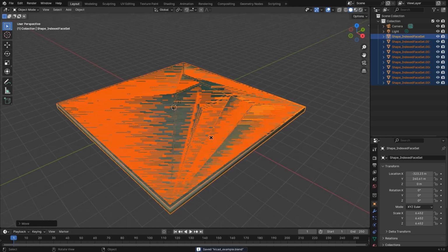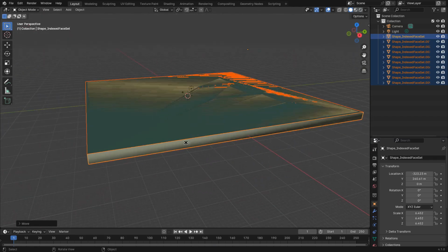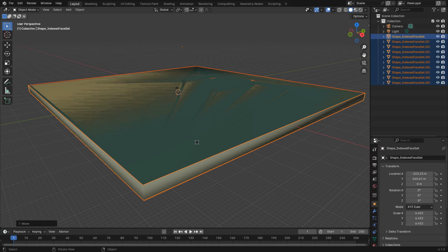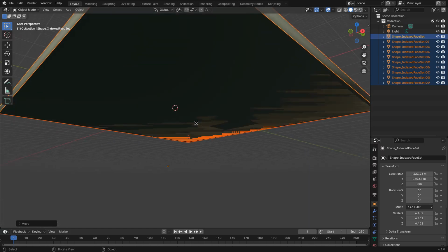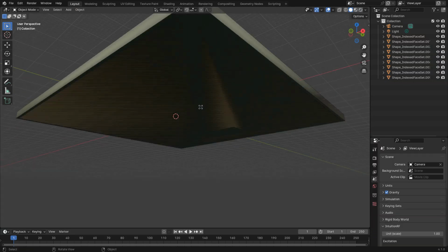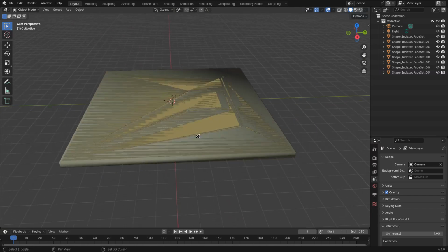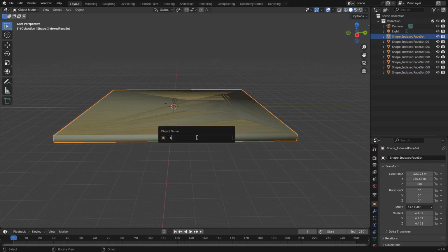Okay, now we have quite a lot of geometry. For this example, I'm going to ignore the finish on top and on the bottom of the PCB, so I'm just going to remove these green layers here and just leave the substrate and the copper planes. I'm going to rename this substrate like this.